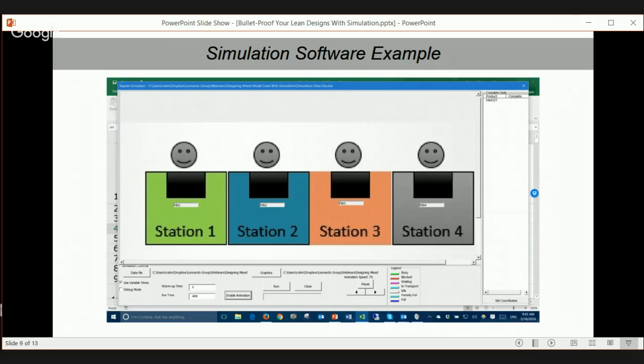We had 4 stations, and the work was balanced evenly. There was a little bit more than a minute of work content. So the takt time here was around 20 seconds, which in retrospect was probably too short. Now, what is Moen doing today? I have no idea. This would be a good candidate for automation, to be perfectly honest. But at the time, we had people doing this with a 20-second takt time. So every 20 seconds, a finished faucet goes into a box, right, onto a pallet.